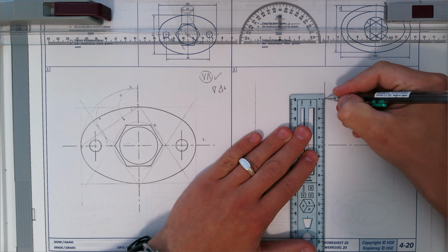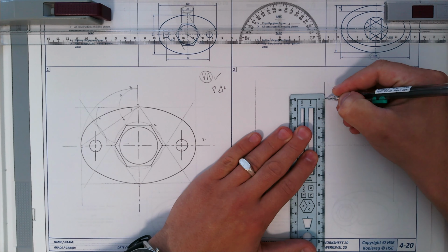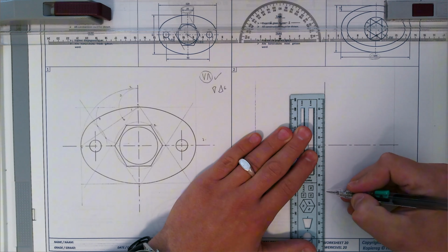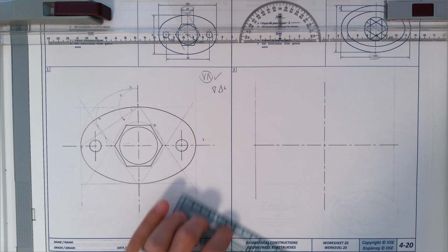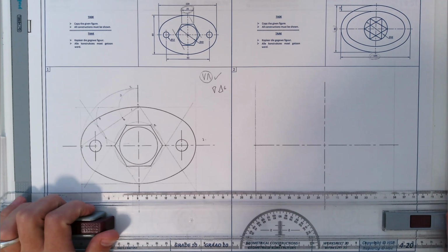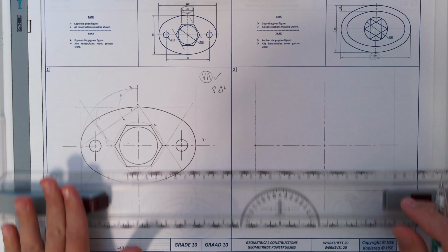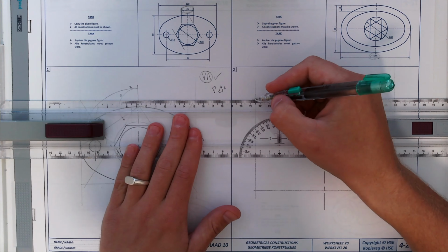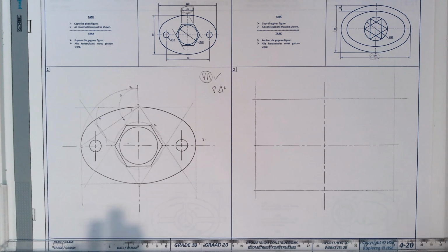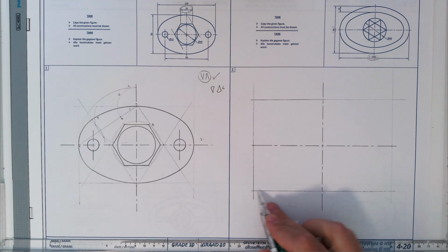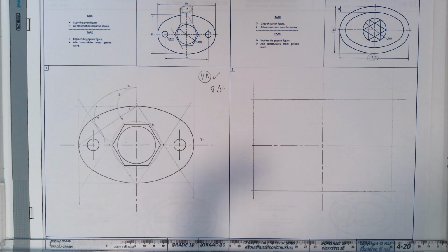48 up, there we're going to make a mark. And then in total it is 96. Yes, 96. So we're going to make a mark there. On those two marks, we're going to draw our horizontal construction lines. And there we go. This is the border or the frame where the ellipse needs to fit into. And it is crucial and very important that you do all of this in construction, which means it is light. This should not interfere with your final drawing.